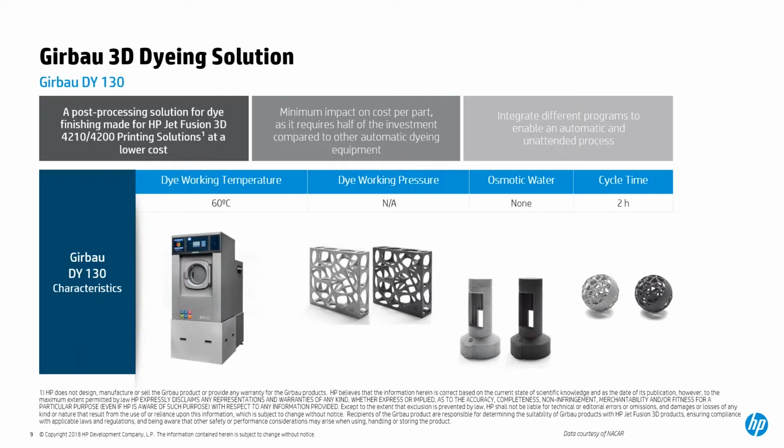In this system, there's also an integrated recycle time that allows recycling the dyeing mix from 5 to 10 times depending on the dyeing selected. And it's also an open platform, which means customers can develop their own dyeing profiles with different temperatures and different times to adapt the process, for example, to a specific material or to get a specific product.